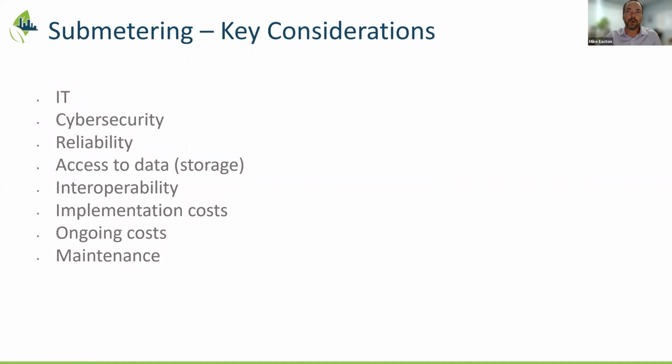And so one of the things that more advanced energy management systems do is they keep continuous track of these meters and automate a response to somebody at the property or a vendor to let them know that there is down communications, and therefore they can take proactive steps to improve that meter communications or fix it, instead of, when you go to look at the data 3 months later and you have zeros or just blanks, that's too late. So I think one of the better technologies is this instantaneous feedback from the systems to let you know if a meter's down.